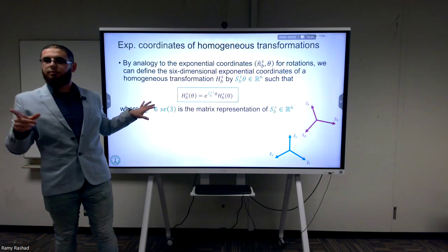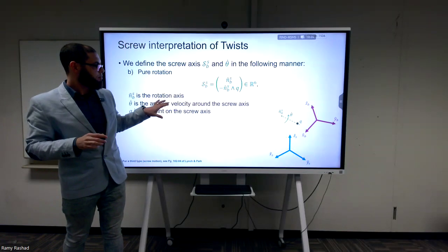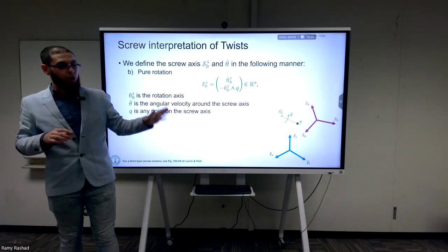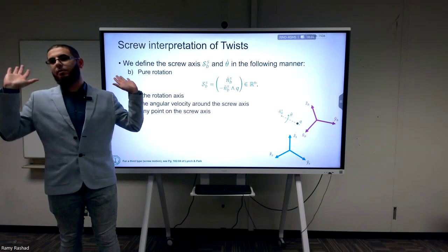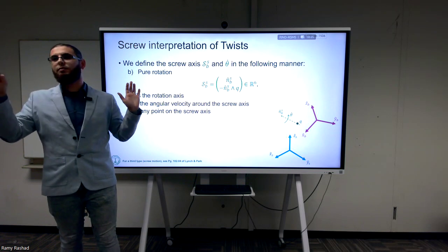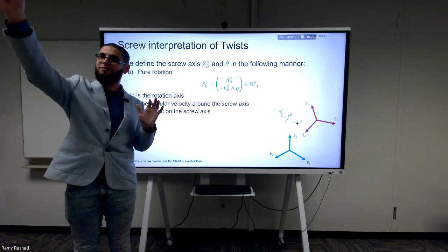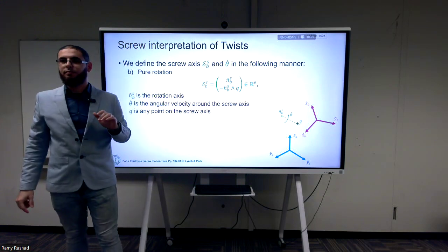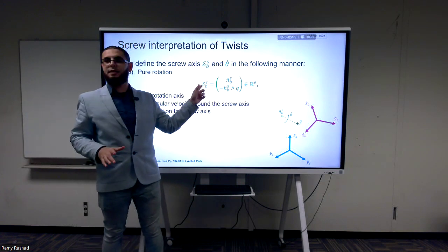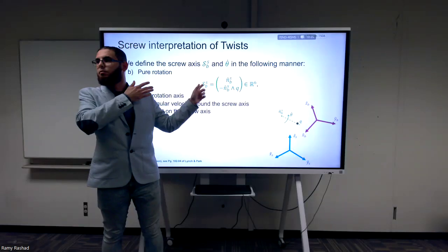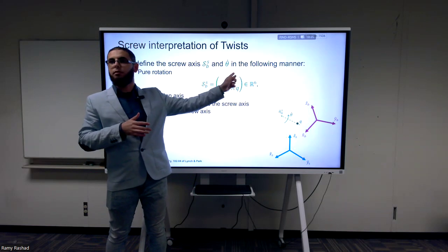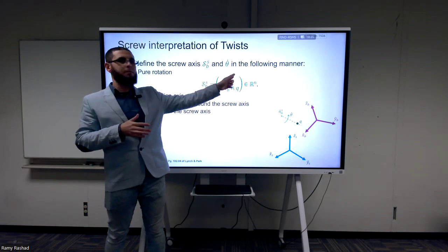One last thing: q is represented as a point, meaning point coordinates according to this axis. It's a point on the axis. You represent it in whatever frame is up to you. It's a point even without talking about the coordinates. It's this point, represented like 3 numbers. When you represent, for example, this screw axis in a frame B, then this will be n in B, and this will be q in B. If you represent it in the S frame, this will be n in S.